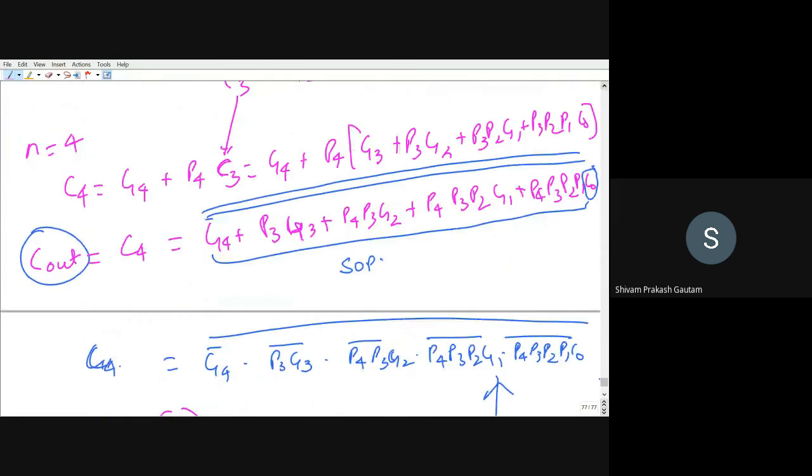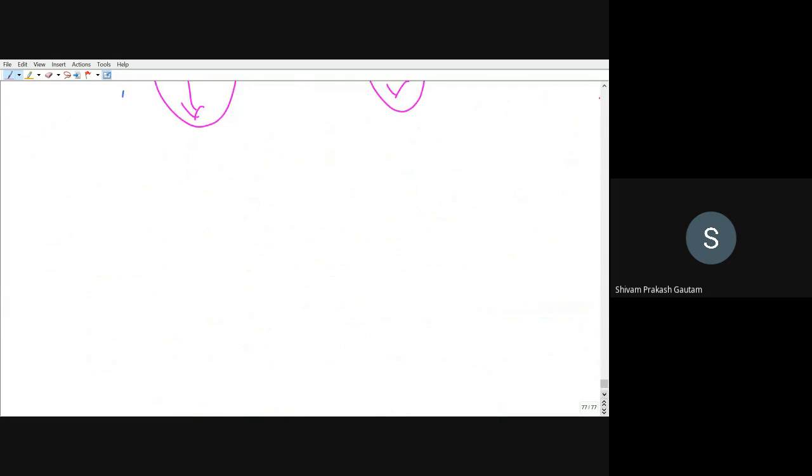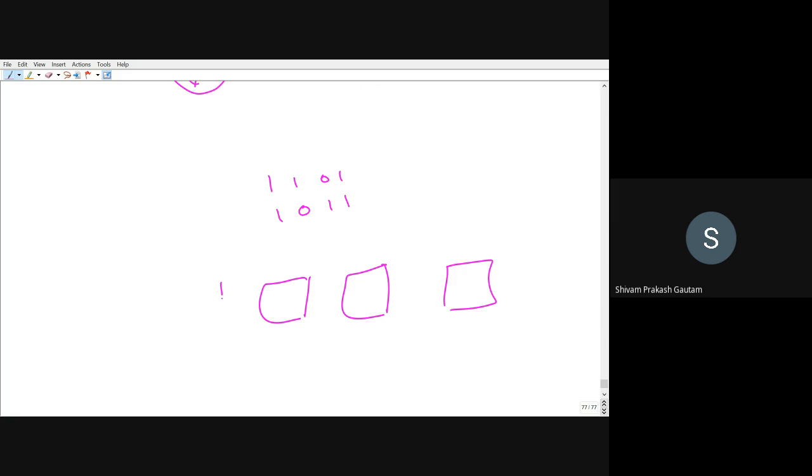SOP part, okay. So here you can see that our final carry out is not dependent upon the previous carries, but it is only dependent upon the input carry, right? So suppose a 4-bit number is given, 1101 1011, and it has been asked to add this number. How did you add this number in previous cases? You added using 4 parallel adders, right?